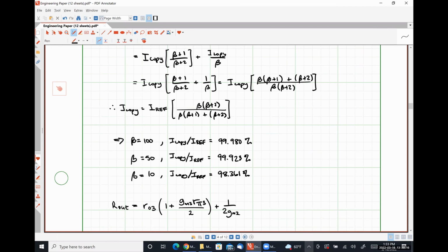So is this purely just data independent of our system? Yeah, effectively. So if we have process variations that cause a lower beta, we still get a fantastic mirroring ability here. The trade-off there, though, is our output resistance isn't quite as high. So we get really good copy currents, but when we connect this to something else, our gain isn't as high.